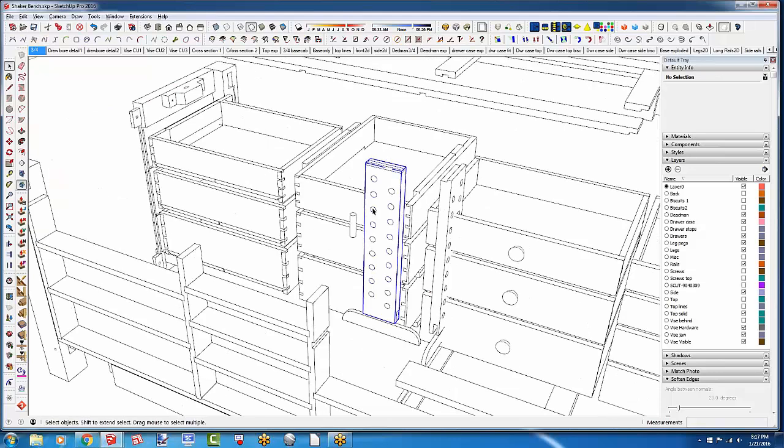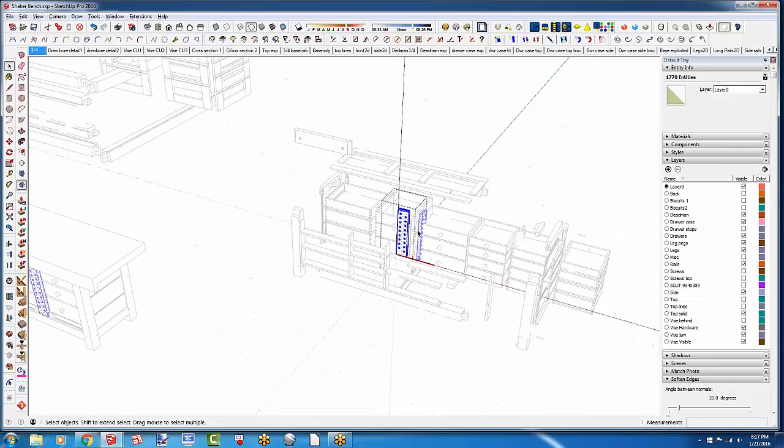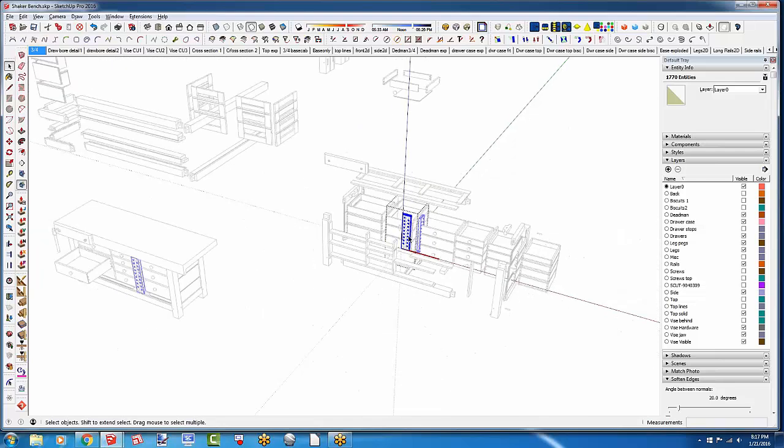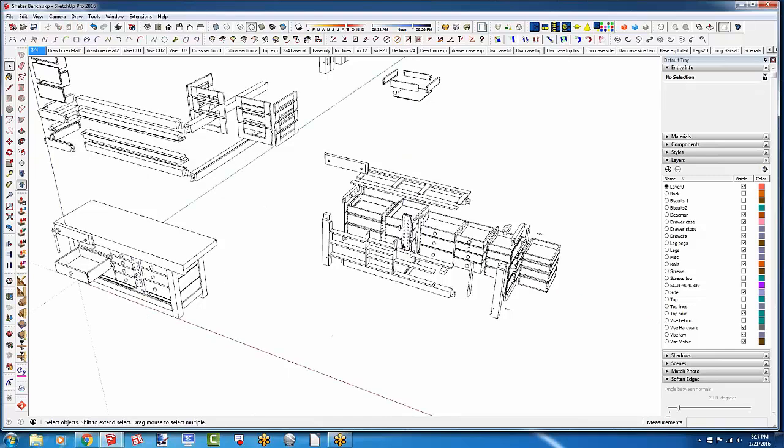So there's 3 copies of that, the board jack or dead man, whatever you want to call that thing, in the model space. So if you started out and made that a group because it was only one, and then you make a copy like this, now you need to change it. You have to go back and find the other copies to make the same changes.